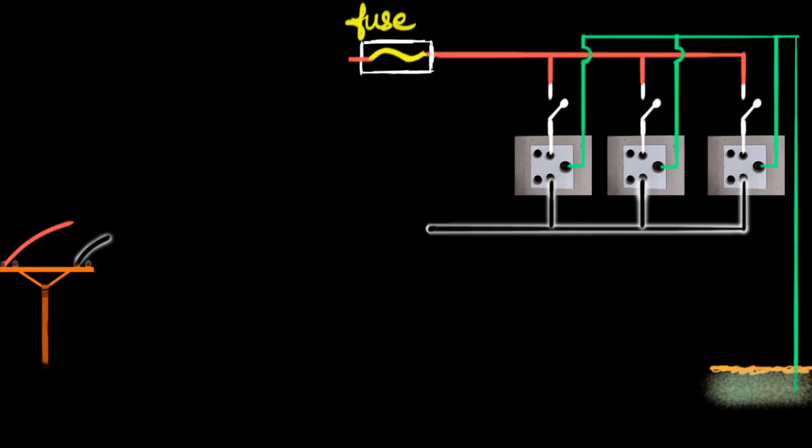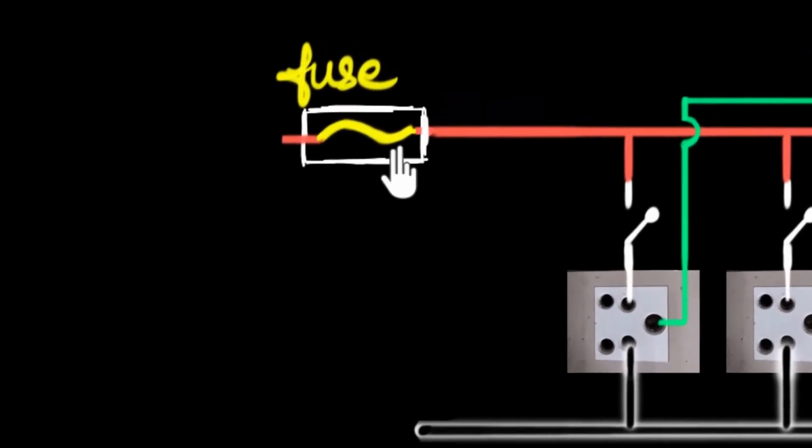So what exactly is this fuse? Well, a basic fuse is just a wire which has the ability to get heated up much quicker than the rest of the wires. So as the current starts increasing in value, the fuse wire starts getting heated up very quickly, and after a point, it's the fuse wire that immediately melts. And as a result, the contact breaks, and this ensures that the entire domestic circuit, the circuit in your house, is disconnected from the mains. And that's how it ensures safety.